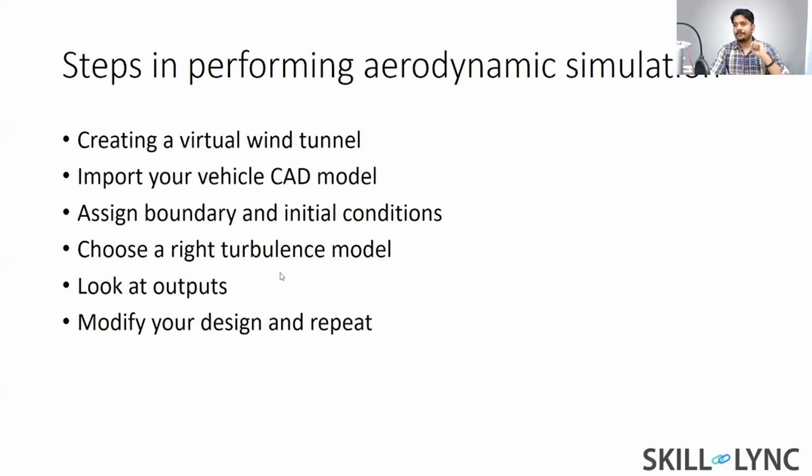From pressure and velocity, you can calculate your shear stress, and then you can calculate your drag forces. From your pressure, you can basically integrate the pressure on top of the surface of your car and get your lift forces or down forces, depending upon what you're looking for. All right. So these are the outputs that you look at.